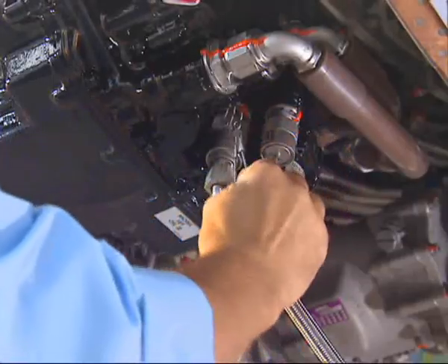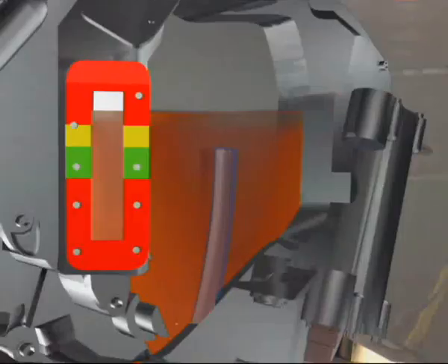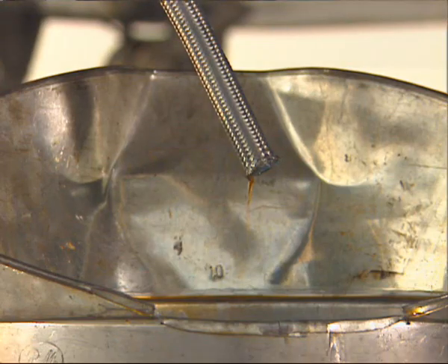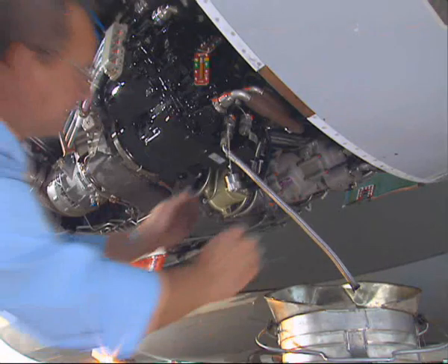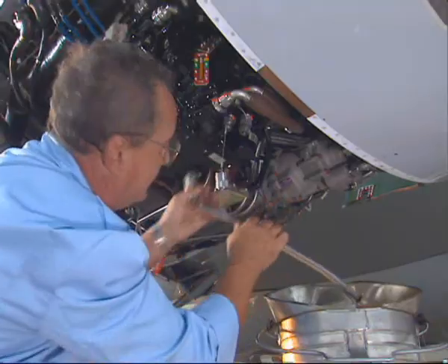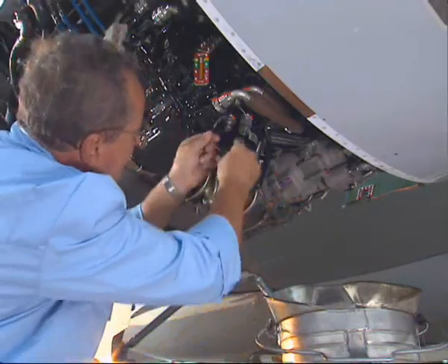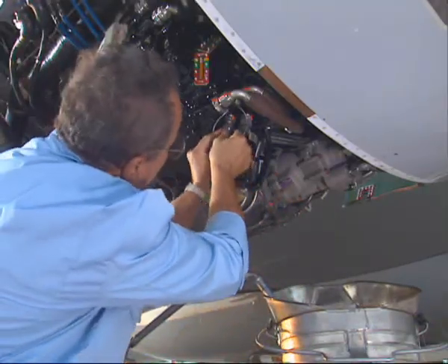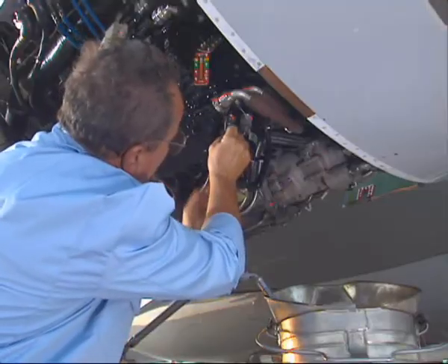Install the dust cap on the pressure fill port. Once the oil level has reached the top of the overflow standpipe, the oil stabilizes at its optimum level at the top of the green band. When only drops of oil come out of the overflow drain hose, remove it. Install the dust cap on the overflow drain port.